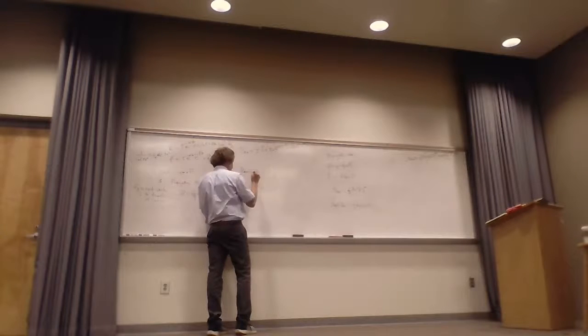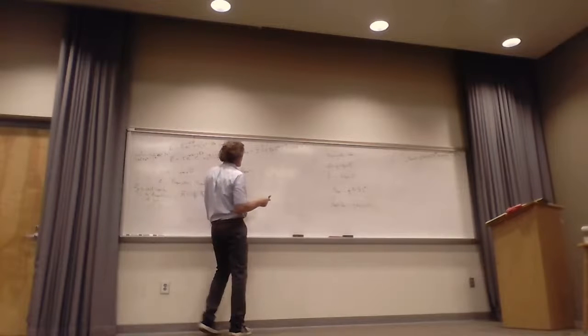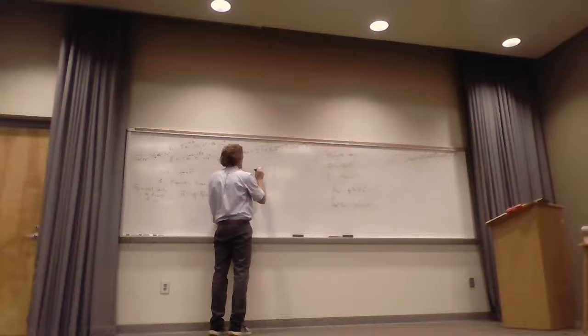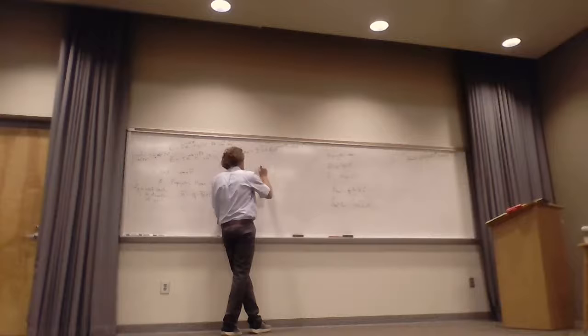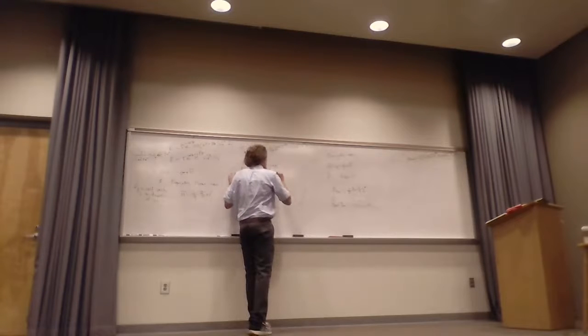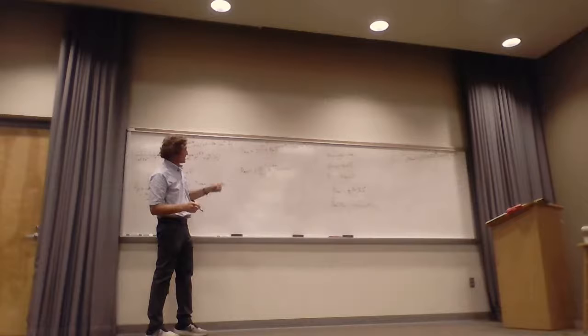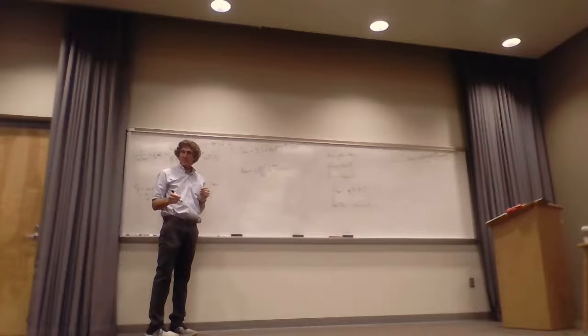That means the average power density is much like what you found out from transmission lines. That's the power flowing, in watts per meter squared, equal to 1/2 times the magnitude of E naught squared over the magnitude of eta, that's the intrinsic impedance, times e to the minus 2 alpha z, times the cosine of the angle theta n, where theta n is the angle associated with the intrinsic impedance.